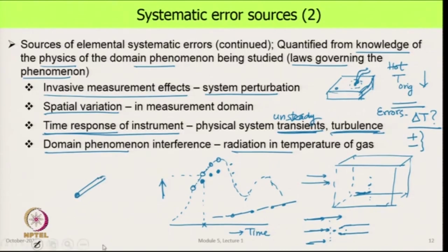So, if we just hold it in the room and say this is the air temperature, well, that is a measurement, but we do not know what are the errors that have come into it. If the room air were cool, say 15 degrees Celsius, and the walls were 30 degrees Celsius or 25 degrees Celsius, then this instrument will not show 15, but 15 plus something.